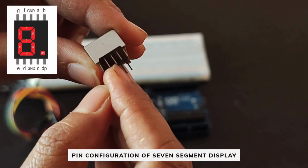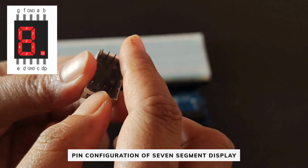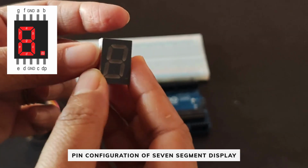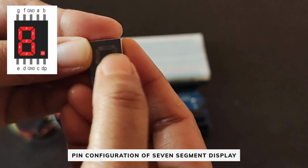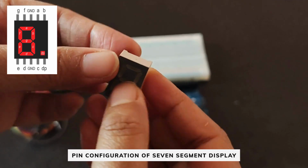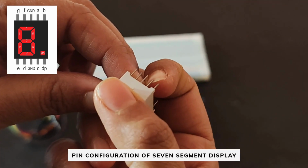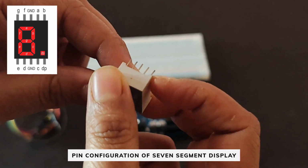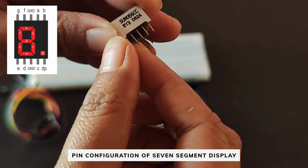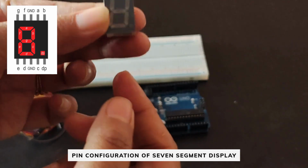So here this middle pin and this middle pin are common pins and we have to connect any one of them to the ground, and the other pins will be connected to the Arduino pins. So like this is segment A, B, C, D, E, F, G. So as a whole, if this is segment A and this is pin A, then pin B, this is C, D, and so on. So we will learn about the pins during the connections.